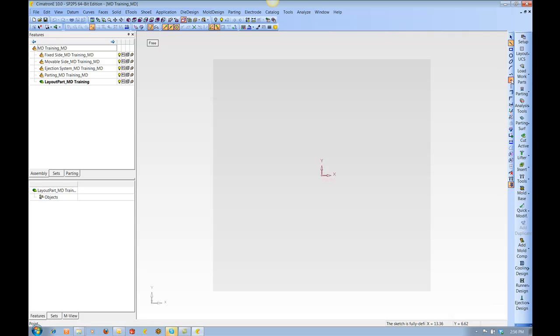Okay, I'm going to go to point, drop one there, drop one there. See how the constraints are lighting up? And see how my cursor looks like a point still, or a crosshair? If I middle click, I come out of that tool, and now I'm in selection tool. That means I could pick this point, I could move it around, I could delete it.